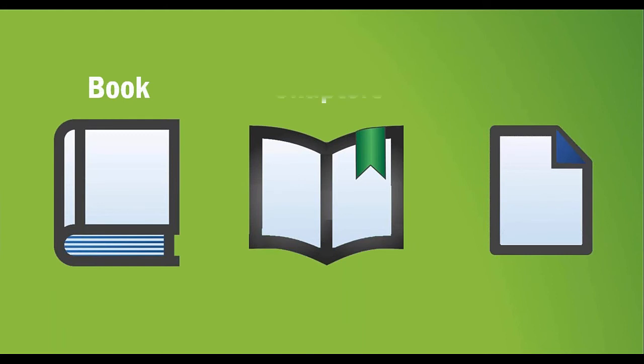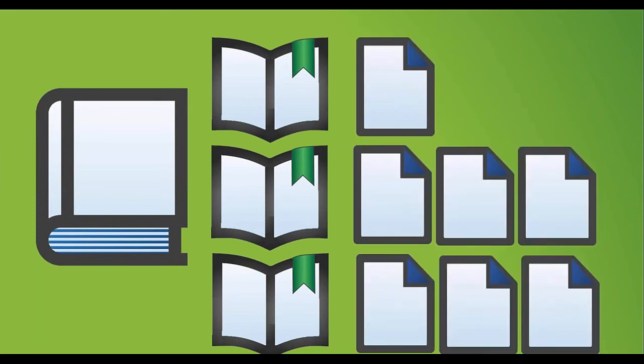The book has a number of chapters, and each chapter is a collection of pages, all the same format with consistent pagination within the chapter. For example, you have 3 chapters in your book, which is your multiplot. The first chapter is the title, the second chapter has plan and profile, and the last one is your cross-sections.